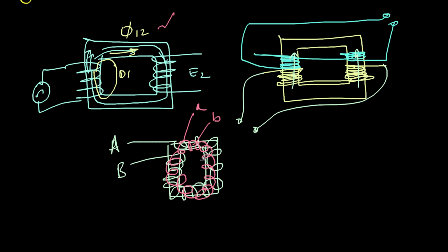But practically when you go to the actual transformer, both the high voltage and low voltage, or both the primary and secondary windings, are actually wound on top of each other in the form of layering. Now you can get a basic doubt. If I do like this, won't it result in a current flow from one coil to the other coil directly? Of course, we'll take care that there is sufficient insulation between these two. Electrically, they are not connected with each other, but physically they are separated by some insulating material.